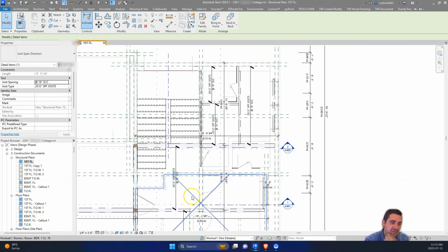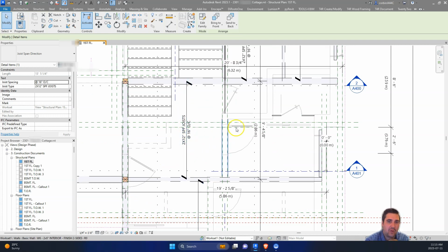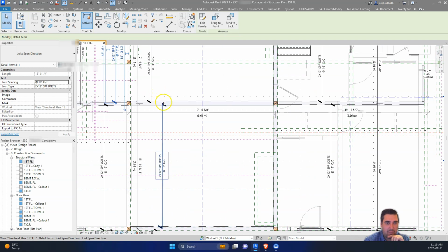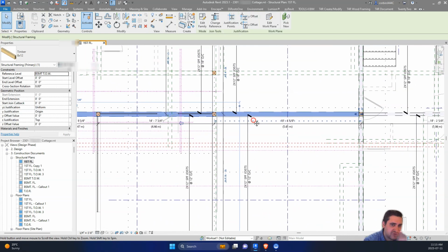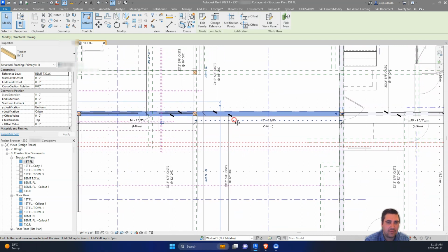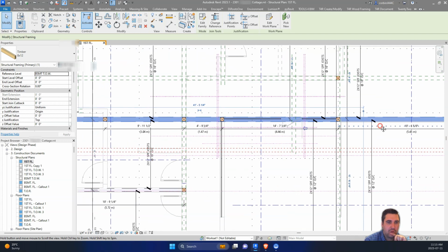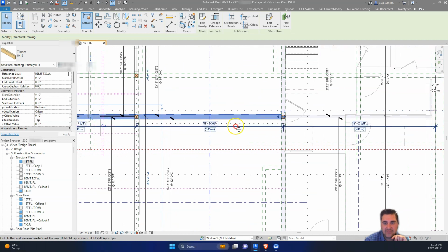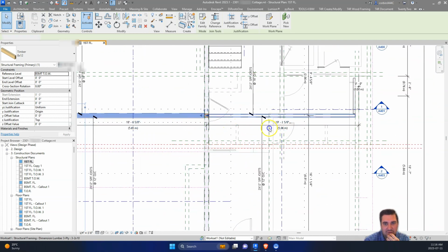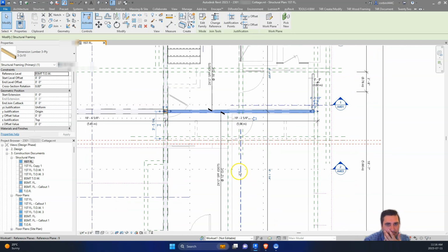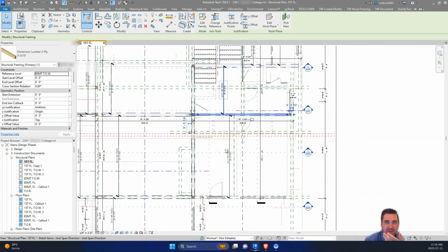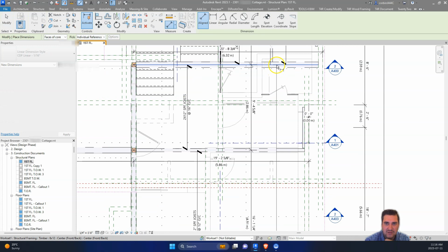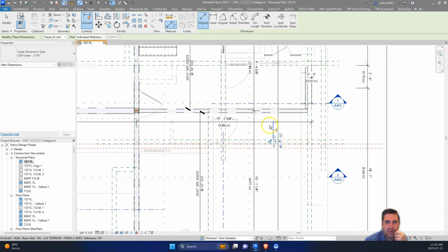So now that we have those joist sizes, we want to find our biggest beam. And again, there's a bit of efficiency potentially in using the same beam size going through. It doesn't always make sense, but we would likely keep this one. We might make this one a different size, but then keep it the same size on either side. So actually this one here is 19'2". So basically the way beam sizing works is we need to understand the whole span. So I'm going to remove this dimension after, but essentially the floor that this beam right here is carrying is 25 feet 6 inches.